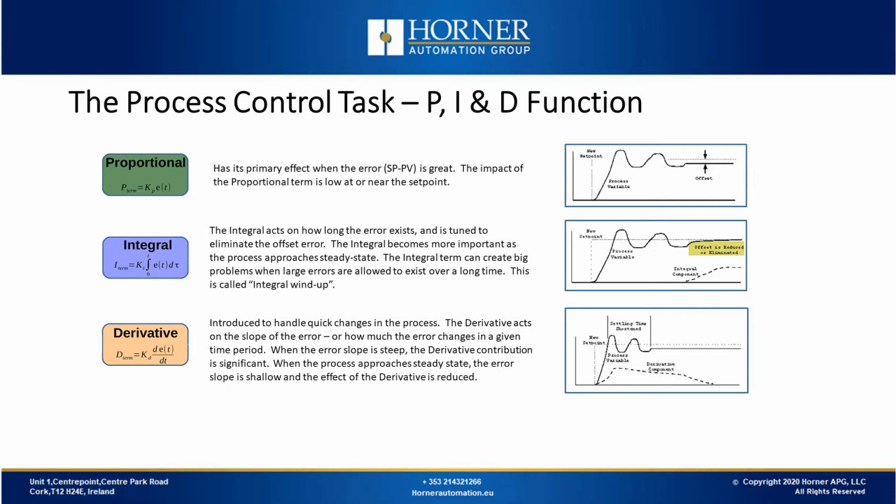We have to be careful with integrals. They can create big problems if large errors are allowed to exist over a long period of time, because the integral term just continues to grow. That's called integral windup. The derivative is introduced to handle quick changes in the process.